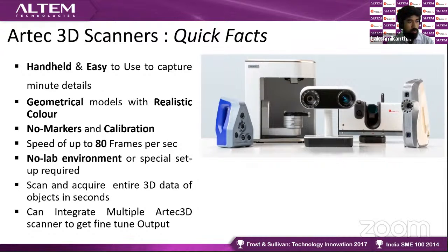But let's assume you are designing something and you want to do analysis of that. That means you are designing some new agricultural vehicle or some machine, and you want to understand the pressure load, or the outlet value of the exhaust system. You can scan that particular system, take the scan model and apply the auto surfacing method to get a CAD model for that. Then the same models can be taken to analysis software like ANSYS or any other software, where we can analyze with different methodologies.